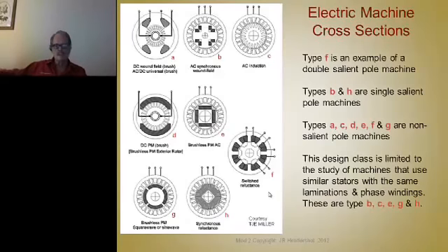But you'll notice that this little chronology starts with the commutated DC motor. Here's your field windings in the stator, and then your armature windings on the rotor. And those are the commutator bars there, and these represent the brushes. So each one of these coils is here's one pole, there's a second pole. So that means that the coils are going to be wound across 180 degrees apart. It'll be a coil there and a coil there, and then pairs of those coils wrapped, stepped all the way around in a lapped fashion.